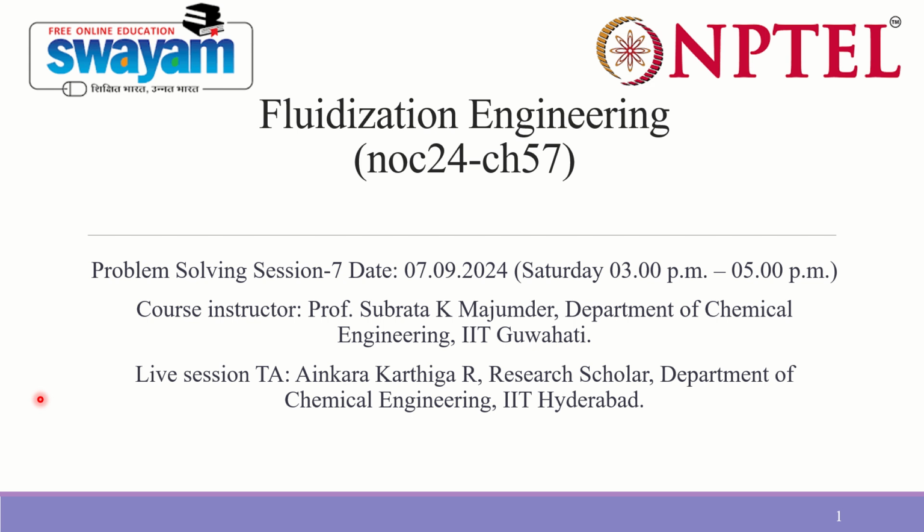And because they have started to move, the contact area between the fluid and solid has increased, which in turn increases the heat and mass transfer rates, depending on the condition which we require in the system. So that is what fluidized beds are.